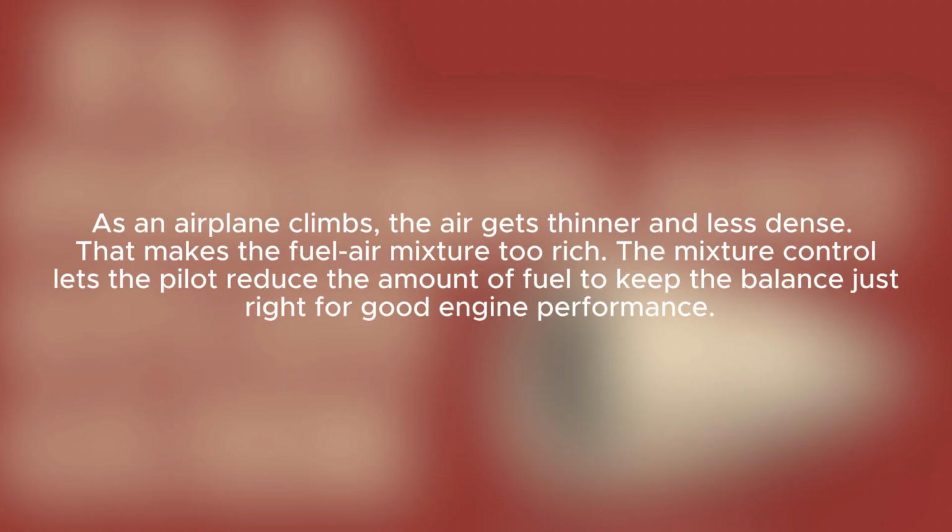Why do aircraft engines have mixture controls? As an airplane climbs, the air gets thinner and less dense. That makes the fuel-air mixture too rich. The mixture control lets the pilot reduce the amount of fuel to keep the balance just right for good engine performance.